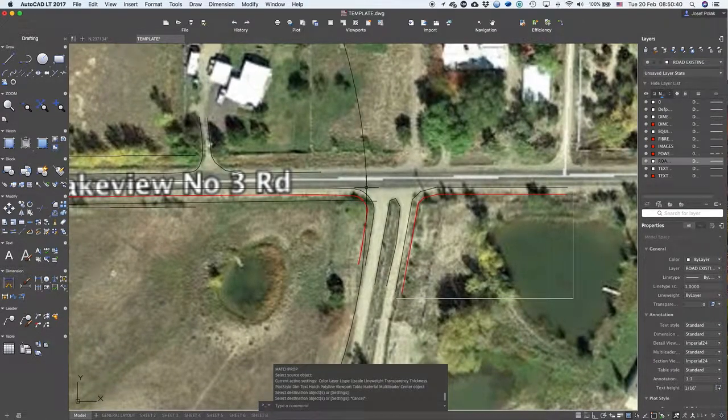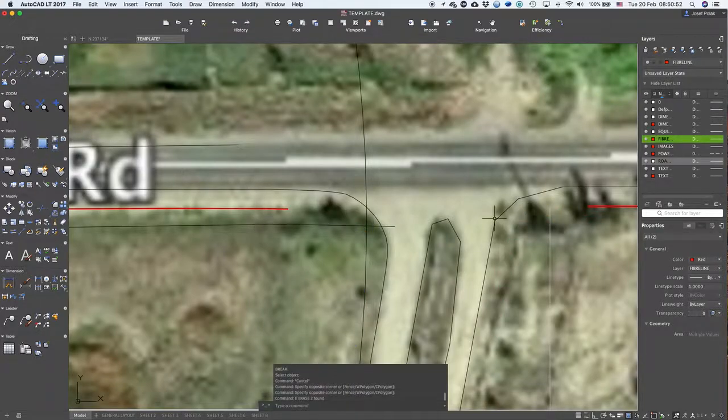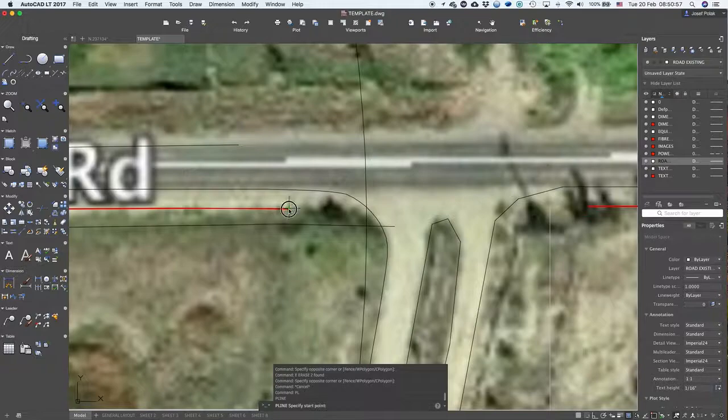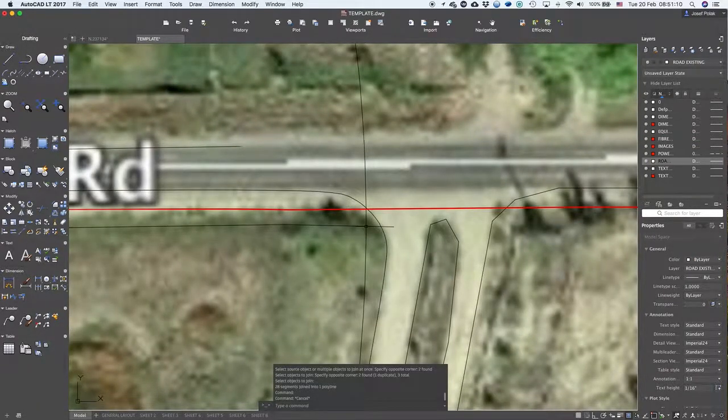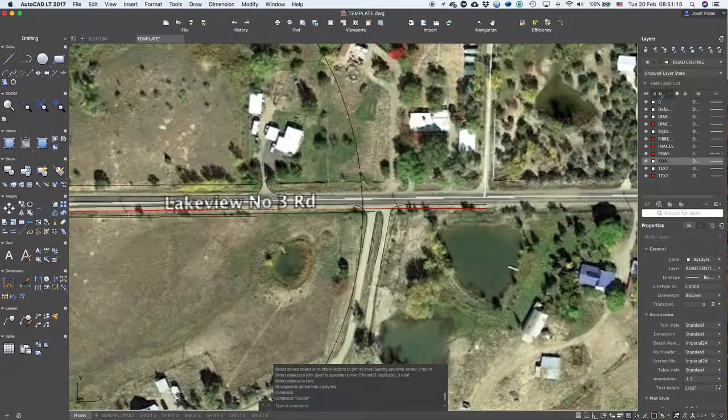Then I just break, because the fiber will go straight through the driveways, right? So I just delete this and create a straight polyline, match the properties and join the lines, Command J. Yeah. So now I have the location of the PED, which would probably be here.